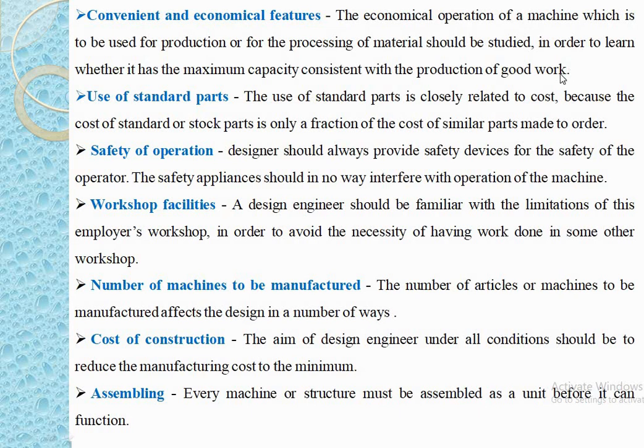The standard or stock parts should be used whenever possible, for which patterns already exist, such as gears, pulleys, bearings, and parts which may be selected from regular shop stocks such as screws, nuts, and pins.